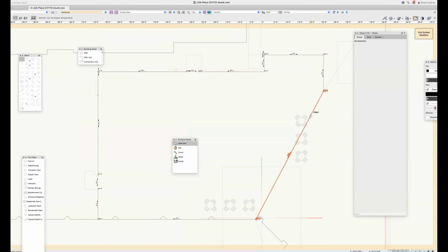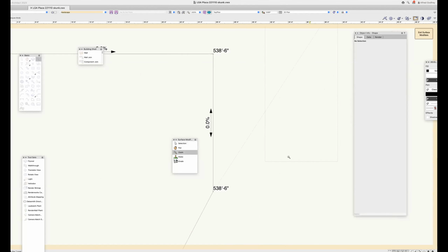He's the one who said, don't bother with stake objects, use the grade objects. And the wisdom of that is you get a perimeter that has all of these important grades all around the perimeter, and you can know what they are because it says so right there.